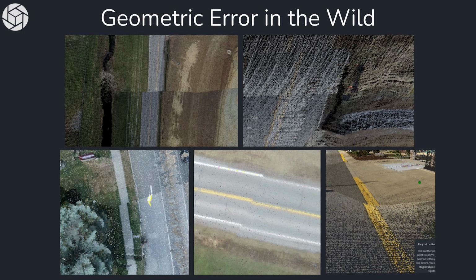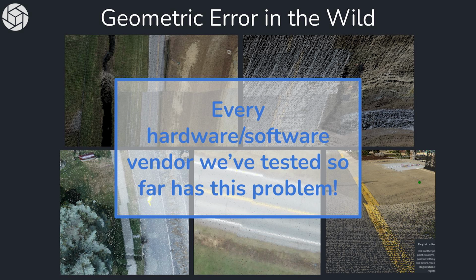And so in the wild, this is what you see with geometric errors in colorization. These are real user data sets where they've collected the LiDAR data and colorized it with the direct georeferencing information, and you've got massive shifts. Some shifts might be on the order of decimeters, going up to 5 to 10 meters. And one thing that we can say definitively is that every hardware vendor we've tested so far in the UAS community has this problem to different degrees, but it's prevalent in every data set we've looked at.